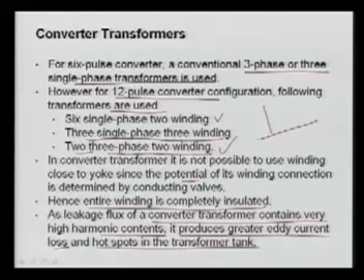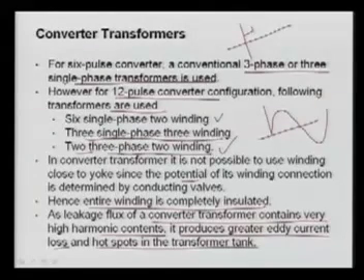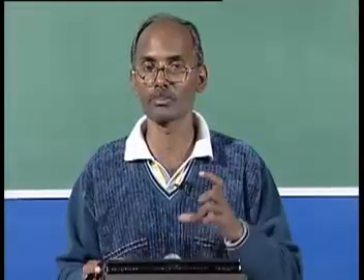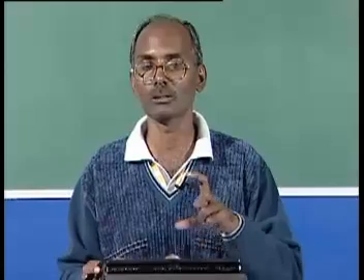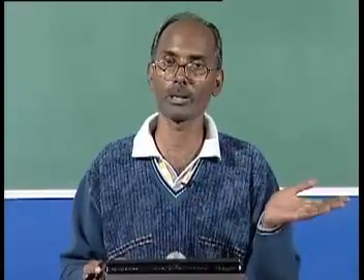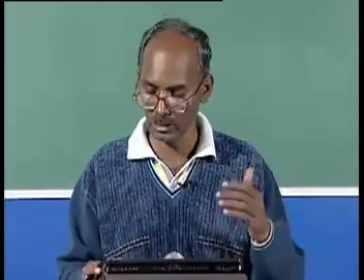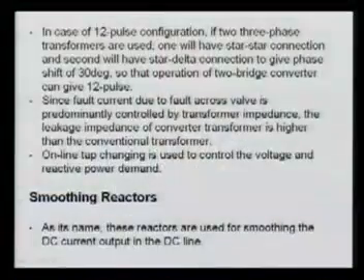Here, for example, the voltage appearing in the normal transformer is like this, but here the voltage will be like this and the current will be like this. It is not perfect. So there are huge surges, and sometimes DC will also appear in the maloperation. Sometimes it is a dead short circuit in the DC circuit. So that appears, and huge current will flow through the transformer.